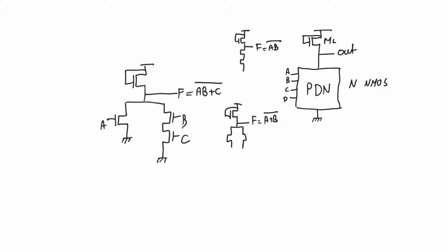And so why do we observe this final bar? Why do we observe this final inversion upon everything? We observe it because the architecture of the logic gate is based on an inverter. And so there is a final inversion that is imposed upon it. If we had started with a buffer, if using a single transistor in the pull-down network had given us a buffer, then we would not have had this inversion at the output.